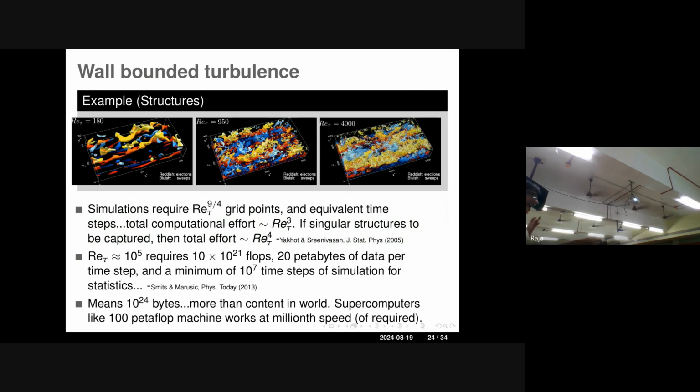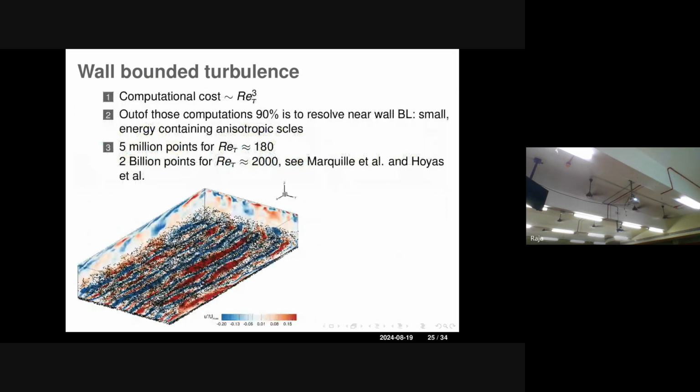And typically, a channel flow of that range requires something like 100 petaFLOP of compute. And that's the challenge we want to compromise. We can't really go with that high Reynolds number, what industry wants, but at the same time, we can't compromise on the size part of this turbulence. So we went ahead and looked at wall friction-based Reynolds numbers of 180 to 400, depending on what kind of configuration you want.